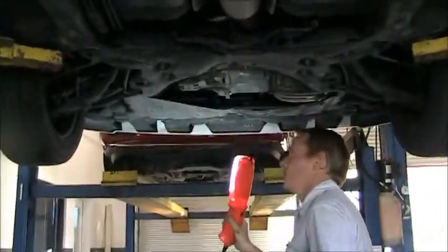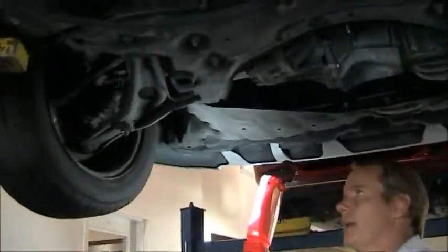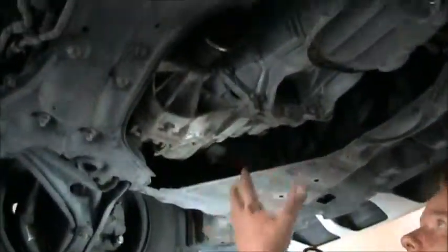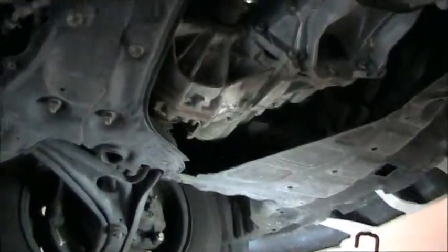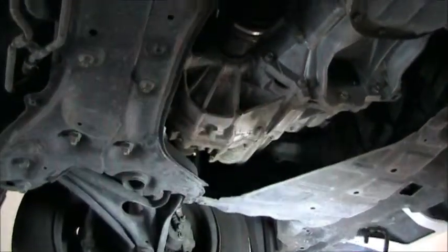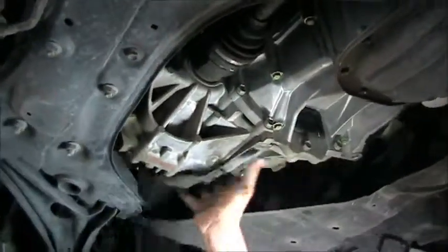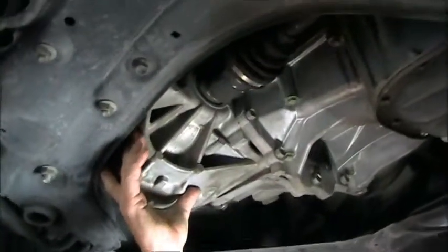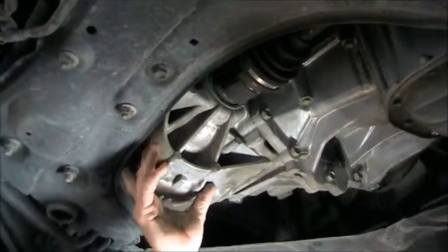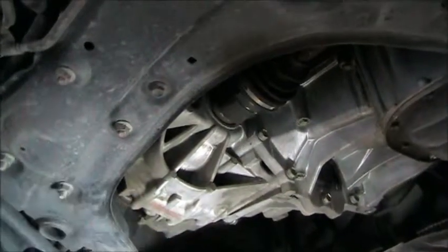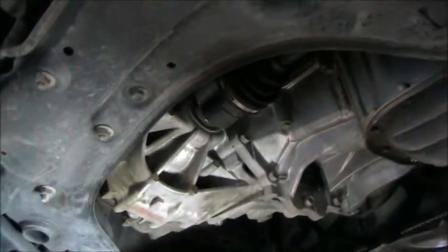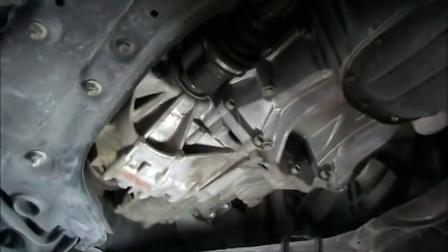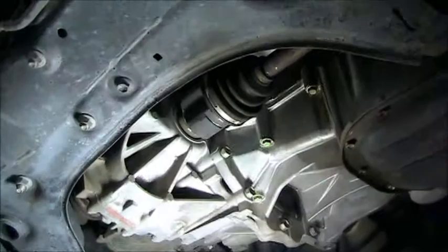This is going to be a picture underneath the vehicle of what a transaxle looks like. Again, this is a manual transaxle, but the bottom of an automatic transaxle looks real similar. It may have a pan for changing the fluid. So we have the transaxle here, transversely mounted. In this section right here, we have a differential. The differential, again, is good to allow the vehicle to go around corners, because when you're cornering, the inside tire is going to cover a lot less distance than the outside tire. They need to go different amounts of distance.